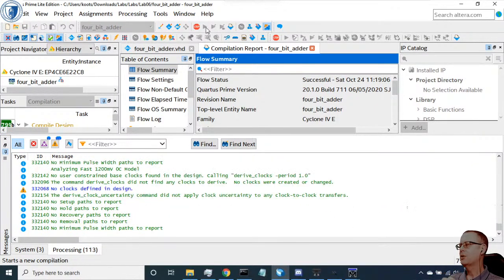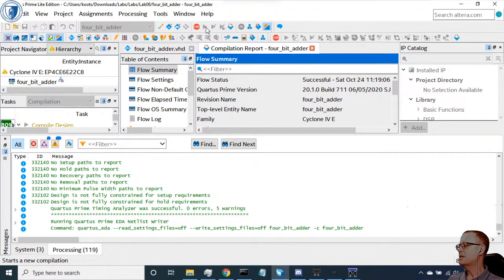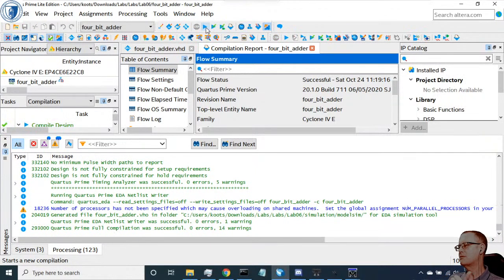Okay, so the code that I just put into the materials section should give you a big boost towards getting it done, but remember, it's not dealing with the subtract component, or the subtract part, so it won't implement everything you need. You need to figure out how to act on the subtract input, negating B in, so you'll need to figure out how to take the 2's complement.